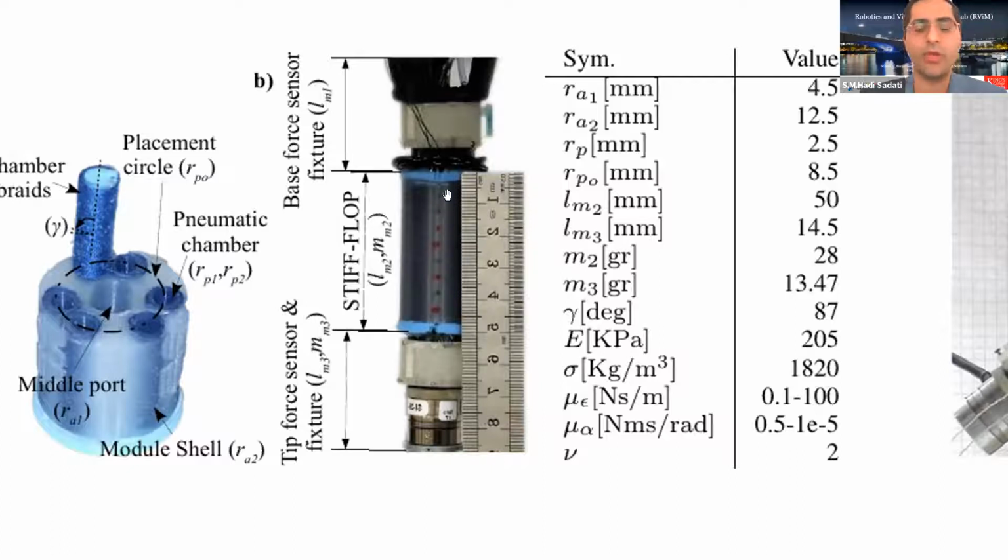But for example, if you look at Octave, the 16% error that you see is associated with 5 millimeters absolute accuracy. And the 4% error is associated with 2 millimeters absolute error. And 2 millimeters for this wobbly structure is actually really good. But in terms of percentage for this structure, it shows large values.